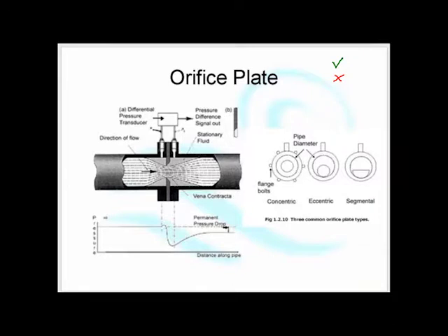Will it work for water with air bubbles in it? Oh no, air bubbles are not going to do good stuff in this. What air bubbles are going to do is build up just before the orifice plate until the air bubble gets big.